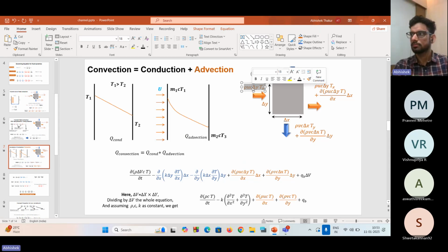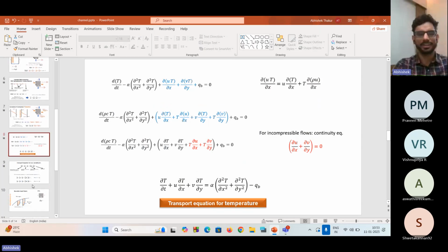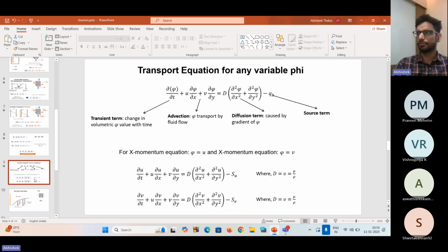In the momentum equation, you have used mu by rho. That is dynamic viscosity also. Yes. We are talking here in terms of kinematic viscosity. You can look into the details, but remember something of fluid mechanics. So it is just diffusion. Diffusion is a new terminology. Viscosity I am more familiar with. So this is momentum diffusion, similar to thermal diffusion.